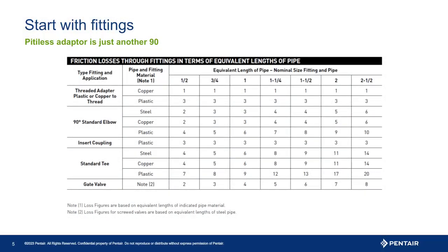Note, we are not calculating friction loss now. We will do so later in the example. Right now, I wish to share a friction loss chart. This one focuses on fittings. The key about fittings is that rather than create a chart reflecting all the flows, this chart simply converts the fitting into an equivalent length of straight pipe to be added to the straight pipe calculation.